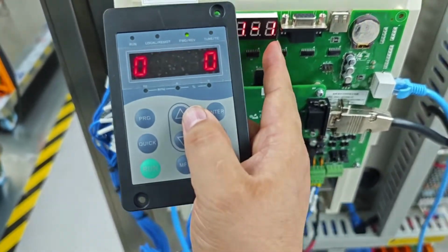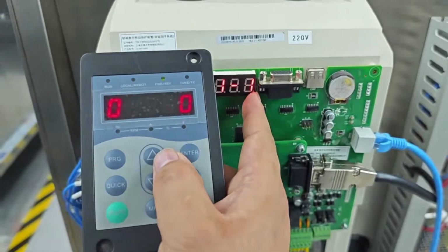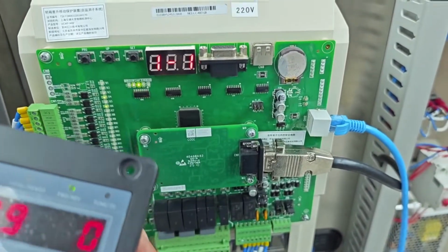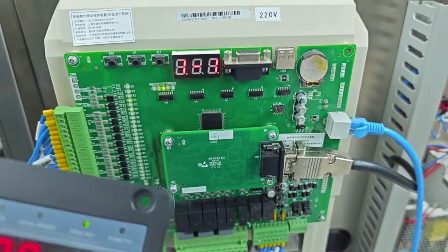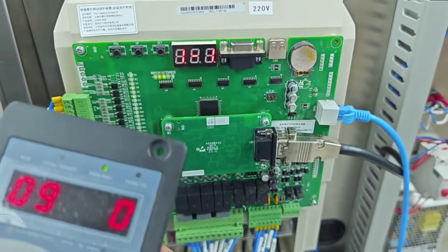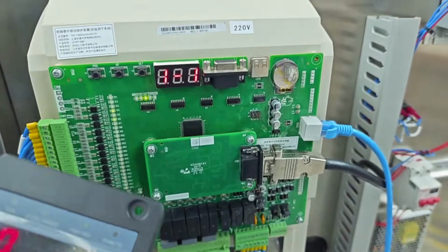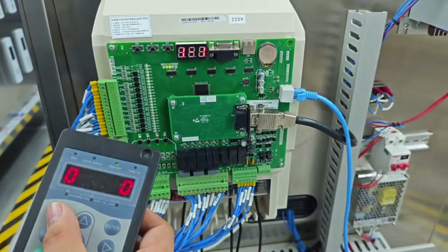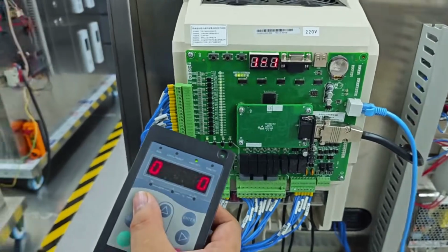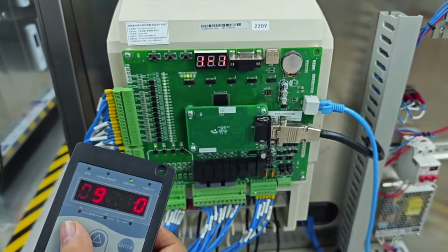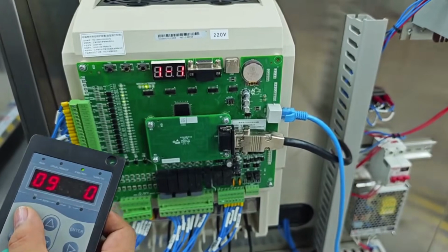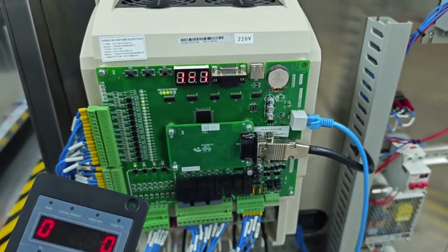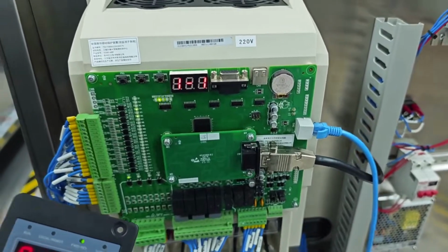Set the 1 to 0, and the mainboard will display fault codes normally. When fault 53-105 occurred, we can do the following testing. First, disable early door opening and releveling to reduce the fault.